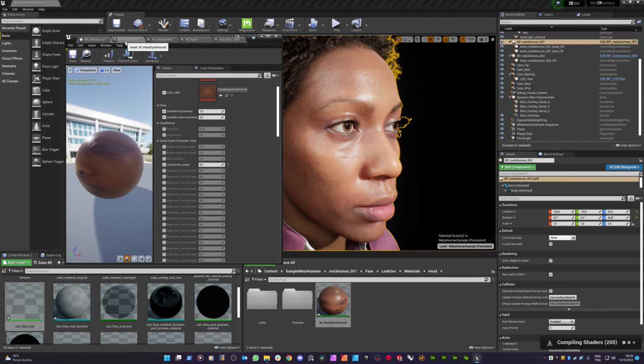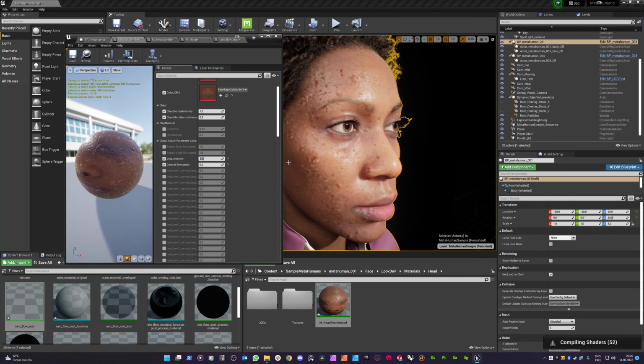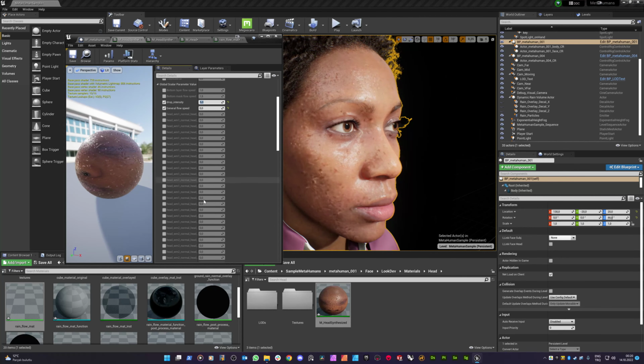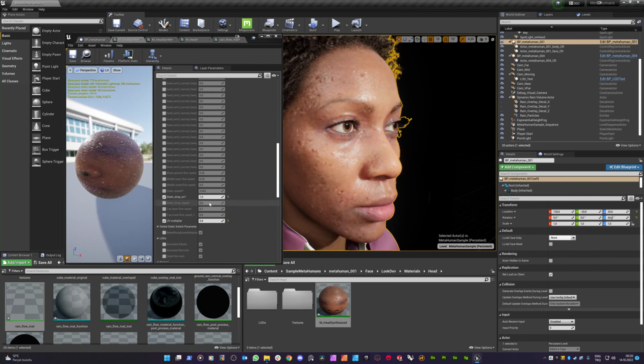After the compiling, we will be having a drop intensity here. Actually, by saving, we have this parameter, and you can see that it's normally 1 by default. If I increase this value, you will see that the drop intensity will be increased. So after that, we can change the static drop speed. It's not good enough, but something like that creates a splash effect.